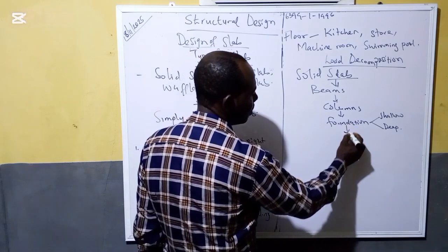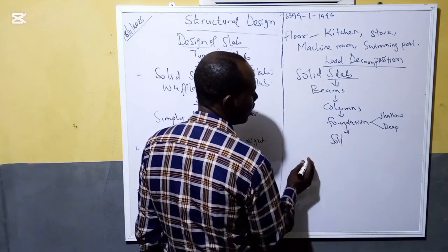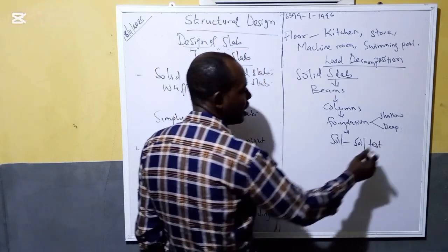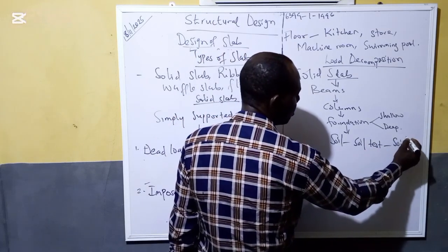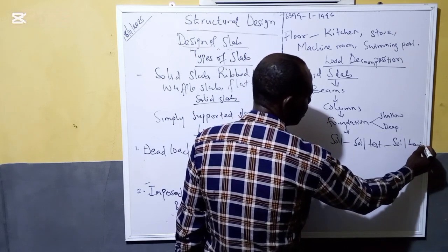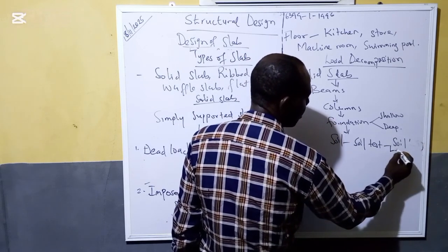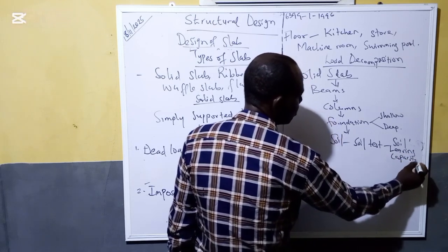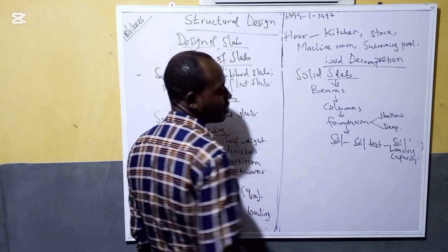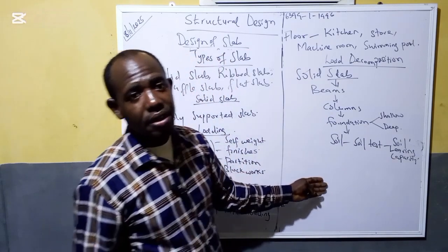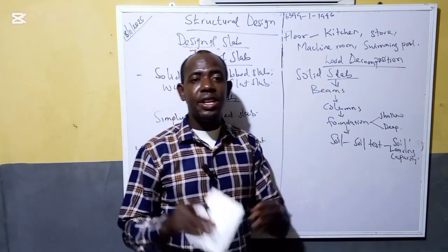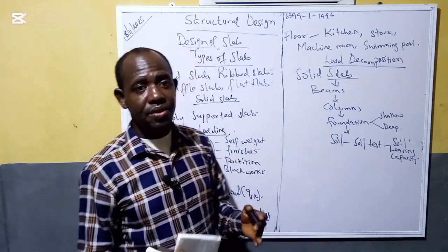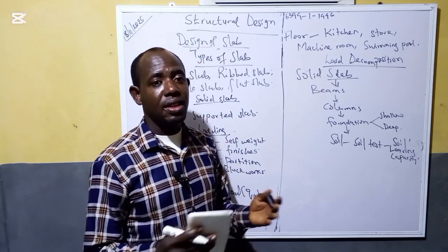So from the foundation it comes to the soil, and this is where you are going to do your soil test. Your soil test is very important, and here you are going to get the soil bearing capacity. For the designer that wants to design, you must know your soil bearing capacity, and the soil test will also show you your soil profile, that is the kind of soil at different levels as you go into the ground.